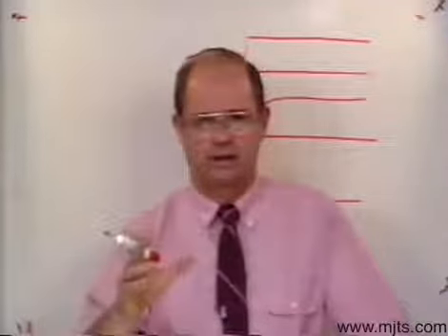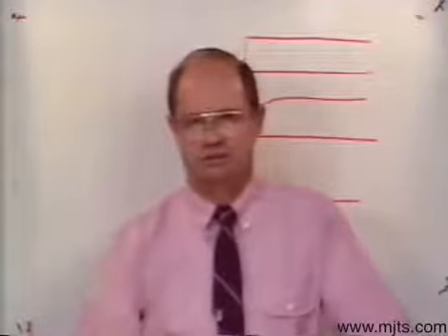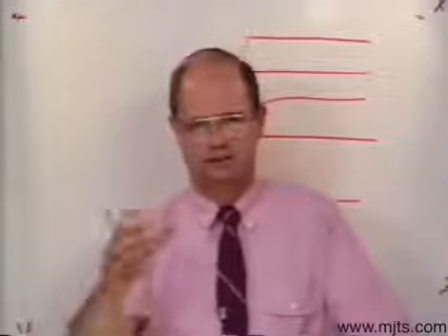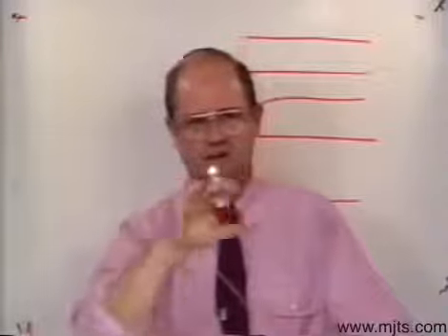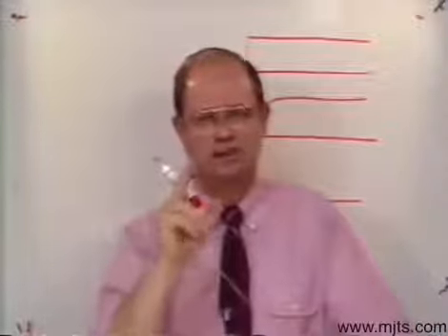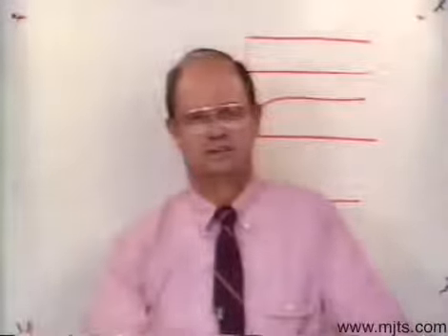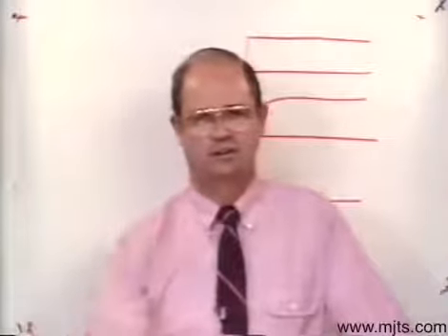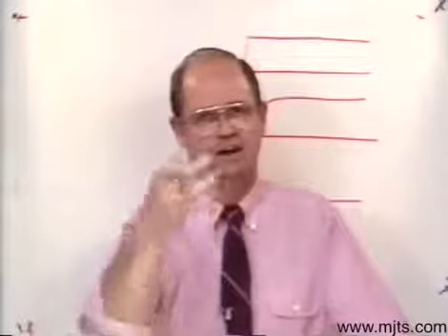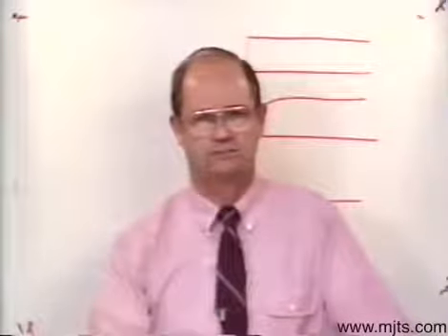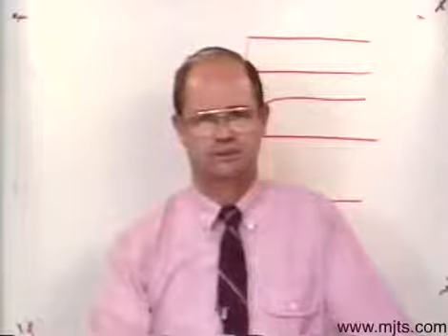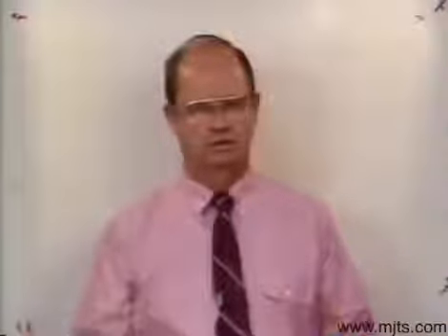For a capacitor, we use just the opposite effect. If the value of the capacitor is indicated and in series, I would use just the opposite effect. And I'll show you why. In other words, when they're in parallel, I'll add them. When they're in series, I'll use the reciprocal method. So let's work some of those circuits. Now let me show you how you'll treat the three components in a circuit.